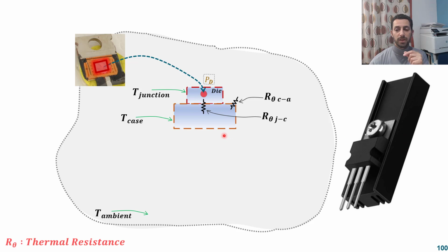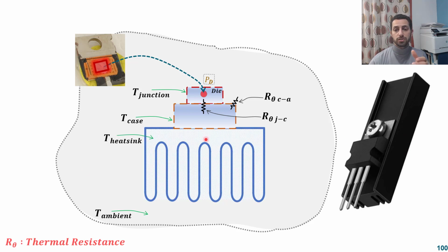have another choice to make, the heatsink here, and there is another component between the case and the heatsink, which is another thermal resistance. That thermal resistance is called case to the heatsink, okay? If we make a good contact between that case and the heatsink, and the surface is finished very well to make a very good thermal contact, for example, we add some grease or some thermal sheets between these two surfaces,